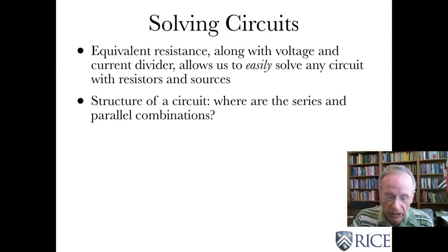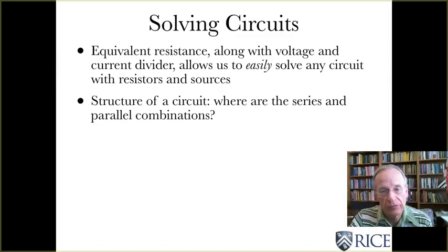That's what we've learned about solving circuits. The equivalent resistance idea comes up because you ask the question, what does the source see? And it turns out, as you can see from all these examples, when you use the idea of an equivalent resistance, along with the ideas of voltage divider and current divider, you can solve circuits rather quickly.